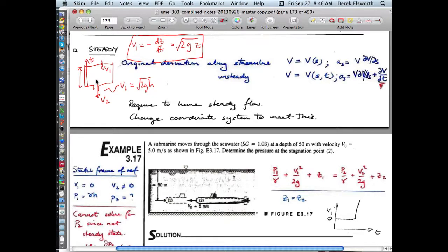And so it is a steady state expression that we use, but of course you could apply that steady state value incrementally to the different states as the level in the water tank draws down. And of course from that you could figure out a graph of height of water in the tank as a function of time. And it's not actually very different from looking at well test equations, where you take a well, you put some extra water in the well, and over time you measure how long it takes for that water level to go back down to the initial water level.